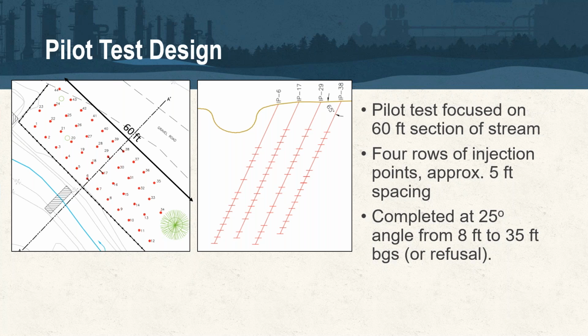The pumps we use are positive displacement, so it's whatever pressure is needed to meet that flow rate. And so pressures are obviously going to vary quite a bit. The injection systems that AST uses on most sites max out at 1200 PSI. That's system pressure, not downhole pressure. Downhole pressures in general are going to vary, say, between 50 and 500 PSI for most sites, once you peel out the system losses. Other sites, bedrock and things like that, pressures can be a little bit higher.